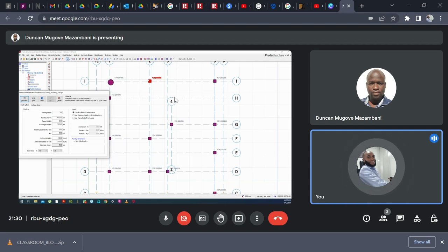Then once you enter into a medium rise building, which is from 6-story to 9-story building, even if the soil is okay above 100 kilonewton per meter square, for a 6-story building you will still be considering using a deep strip foundation. But once you enter 7-story, 8-story, 9-story, you should consider using a raft foundation, even if the soil bearing capacity is okay.